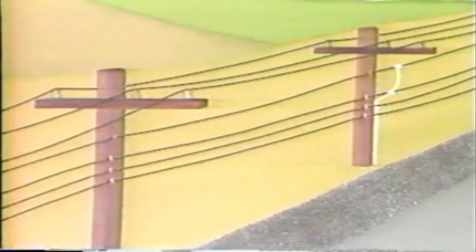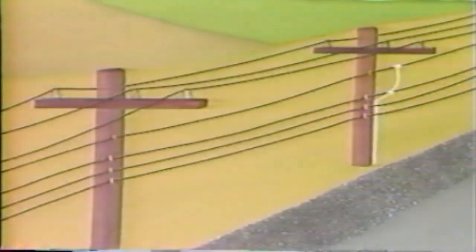Well, the vast majority of faults on overhead lines are due to lightning. The high voltage flashover to ground creates a flow of fault current which trips the breaker on overcurrent or perhaps overvoltage. However, the fault is only temporary in nature and will be removed as soon as the breaker trips. Therefore, when the breaker is reclosed by the reclosing relay, the fault will have disappeared and the line can continue operation as normal. However, if the fault is permanent, for example, perhaps a tree limb has fallen onto the line, then the protection will sense that the fault condition persists and will trip the breaker again.